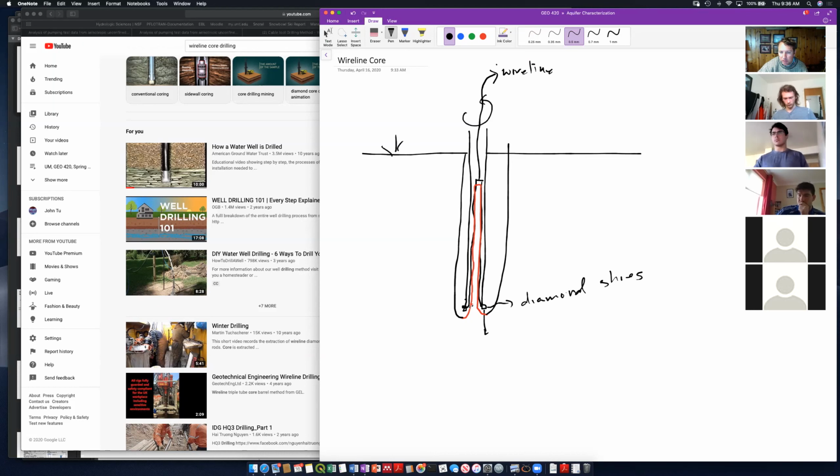It's got some special teeth down here that hook on to the bottom of the core. They break this column off and you pull it up and you've got a core tube sitting at the surface, just like in the GEO probe. You got this tube and it's got your core in it. You send another one of those tubes down in, it hooks in, and you start drilling again. All right, so you advance about 1 to 3 meters at a time. And then you pull core. And then you advance again.